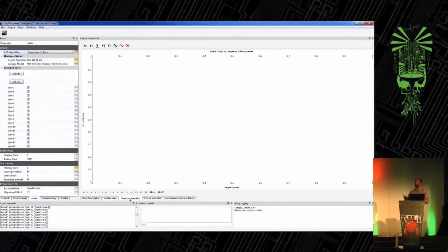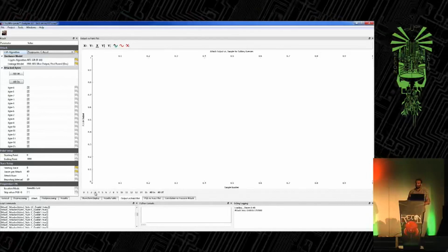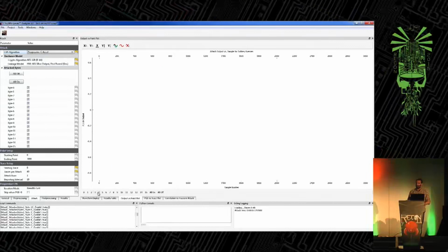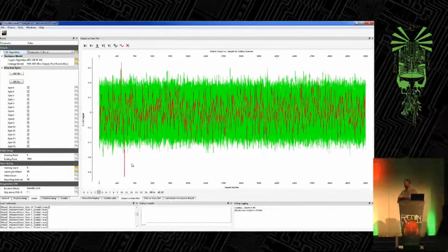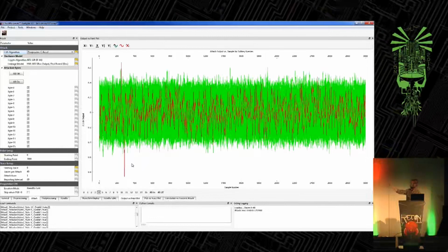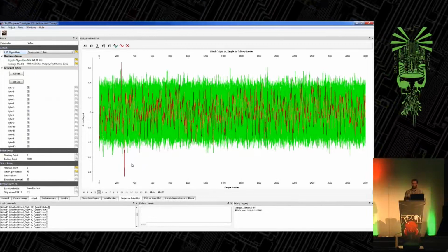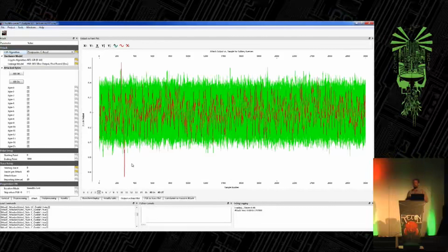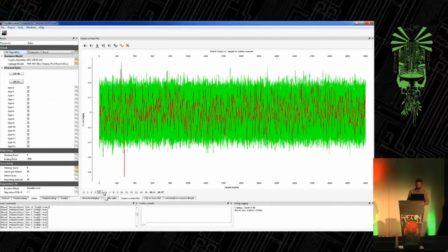One of the other questions people always ask is, how do we know where the encryption is happening? The analysis itself gives you some of those answers. This is graphing the correlation, looking for that linear relationship, and this peak is at various points in time as it's executing instructions. Between sending data to the device and getting data back, it's running the encryption algorithm and doing the operation I'm targeting.